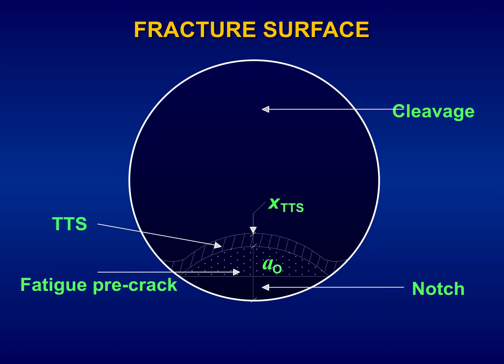This is a fracture mechanics approach in which the hydrogen-assisted microdamage represents an extra crack prolonging the original fatigue pre-crack, a mechanical fatigue pre-crack, and an environmental crack, a posterior crack produced by hydrogen-assisted cracking in the form of tearing topography surface.